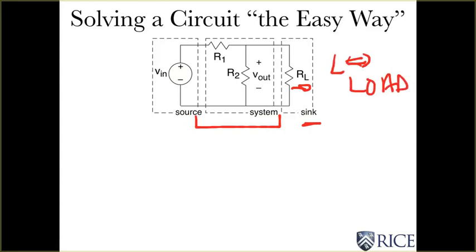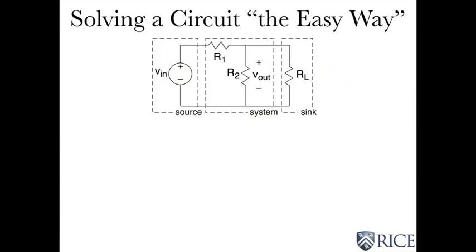And the question is, does the relationship between Vin and Vout change because there's a load resistance out there? You might say, well, geez, this voltage here is the same as that voltage there, so probably it doesn't change. Well, that's not quite true. That's because these are in parallel, and these voltages are actually across the parallel combination. There's something to figure out there. I've essentially given away how you analyze it.